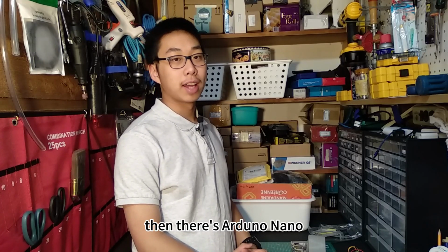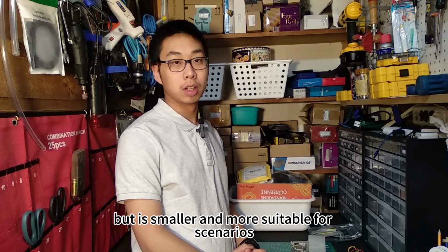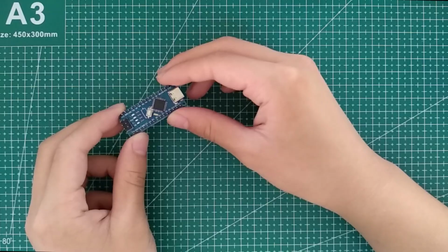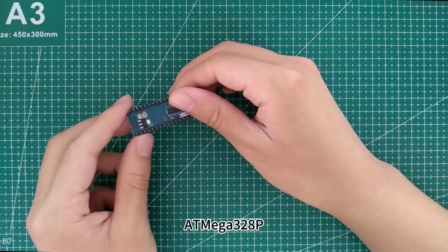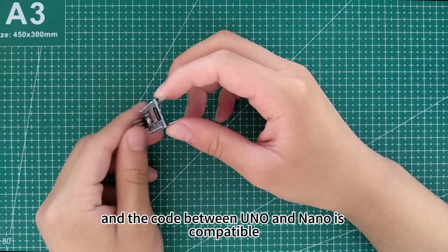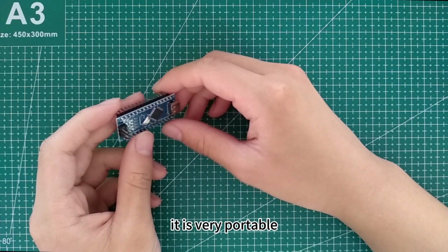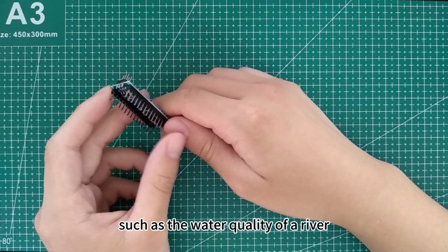Then there is Arduino Nano. Arduino Nano is similar to Arduino Uno, but is smaller and more suitable for scenarios with tighter space constraints. This microcontroller is also based on the ATmega328P and has similar functions to Uno, and the code between Uno and Nano is compatible. Because the Arduino Nano is powered by a battery, it is very portable. It can be used outdoors to collect data, such as the water quality of a river.